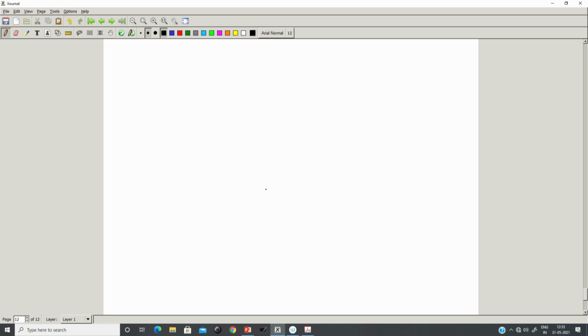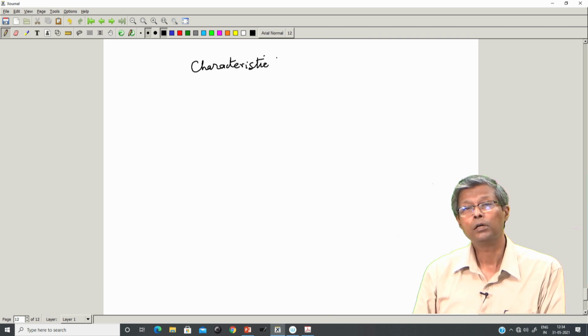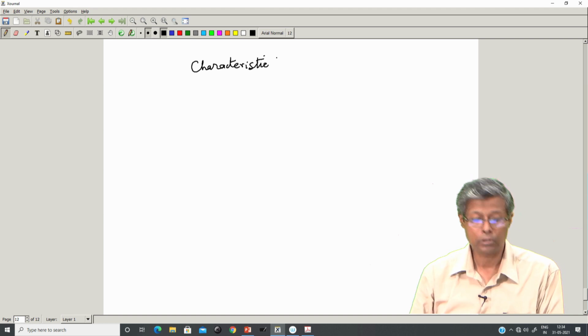So, following this, we write down the characteristic equations for the NRD modes. They are obtained by equating the tangential electric and magnetic fields at the air dielectric interface and using the Helmholtz equation in the dielectric and the air regions. Please verify them from the previously given field expressions. So, equate the tangential electric and magnetic fields at the air dielectric interface and use the Helmholtz equations, which will yield the characteristic equation for the NRD modes.